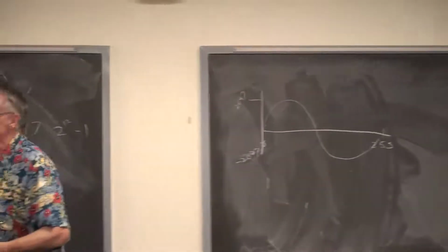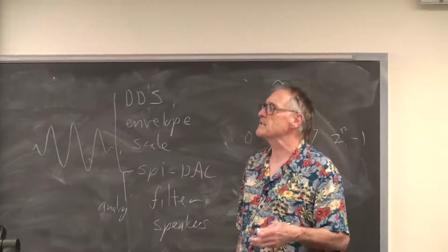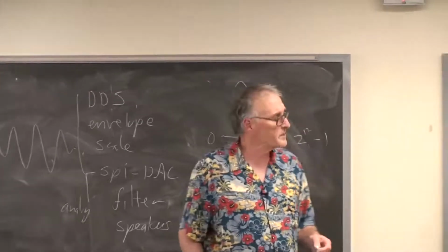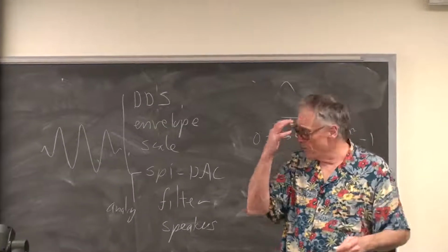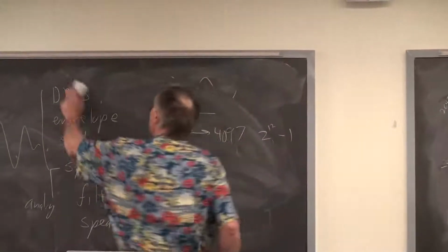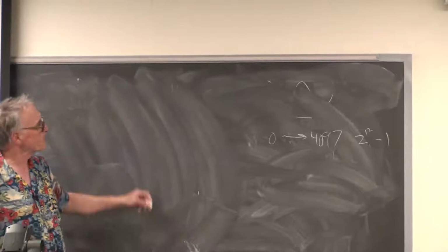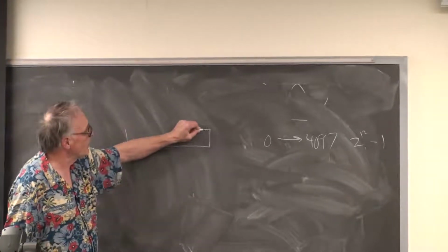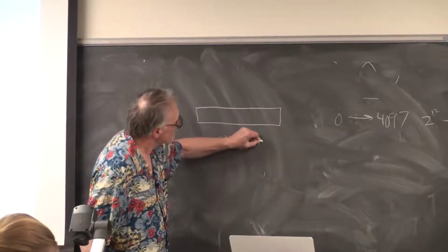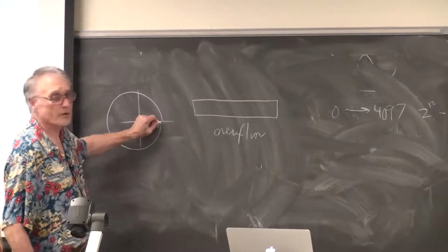You're going to want to choose samples from that sine wave to output to the DAC, and you have to choose at least 8 or 16 per cycle of the sine wave. So 30 or 40 years ago, somebody thought up this system which goes like this. And the central abstraction is that a variable overflow is topologically equivalent to one rotation of a phasor.